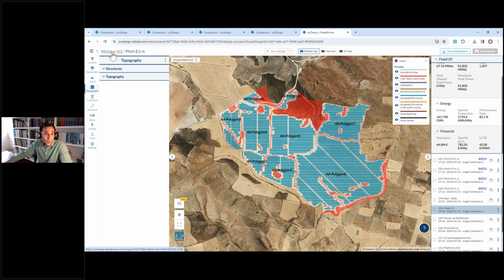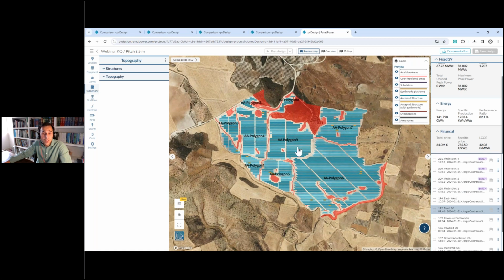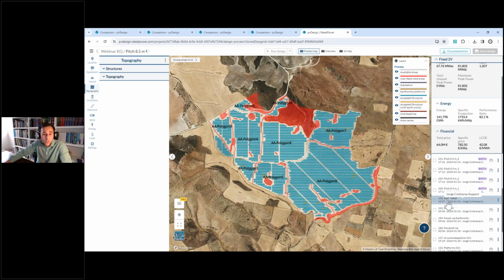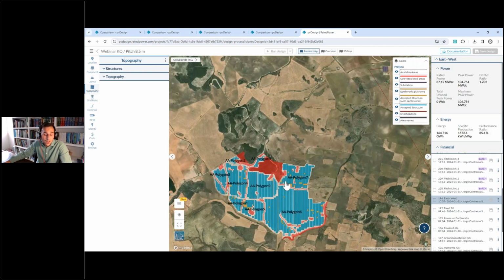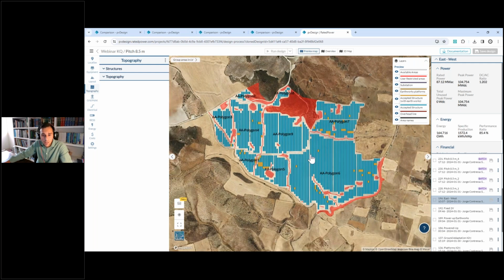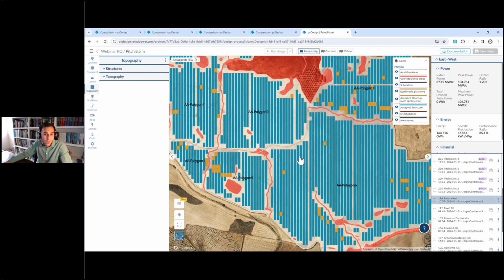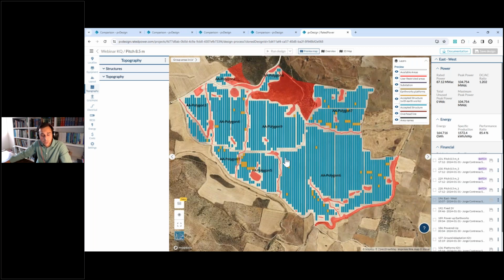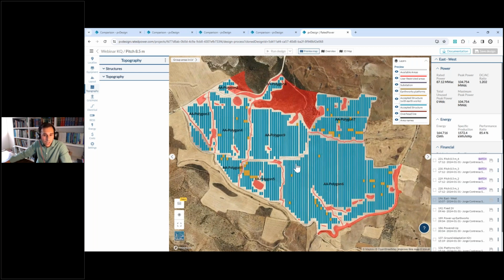So yeah, this is a good approach. And the third one could be, okay, if I go to a fixed structure, what if I decide to go with east-west structures? This is a new trend to perform your PV plant, which is applying a two-direction fixed structure oriented to the east-west in order to increase the maximum capacity and so the GCR.